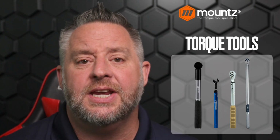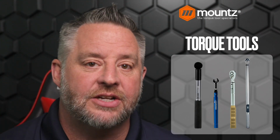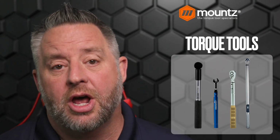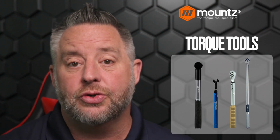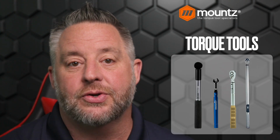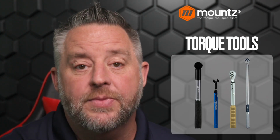Next is going to be the digital wrench, a digital torque wrench. And this acts very similar to a click wrench. However, there are more audible and visual signals that you may be getting close to your torque value, but there is no guarantee that where you stop is going to be the torque that you initially are looking for.